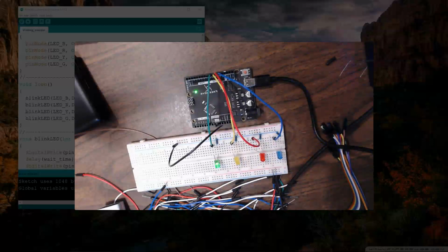And so you can basically see here, this is the top of the loop. And as we get down to the bottom of the loop, it goes right back to the very top. So that blink function works to blink them individually. Again, if you wanted to blink them all at the same time, you'd have to modify them so that they all go high, then there's one delay, then they all go low, and then there's one delay. But this is what you want to play around with. See what you can start building and doing.